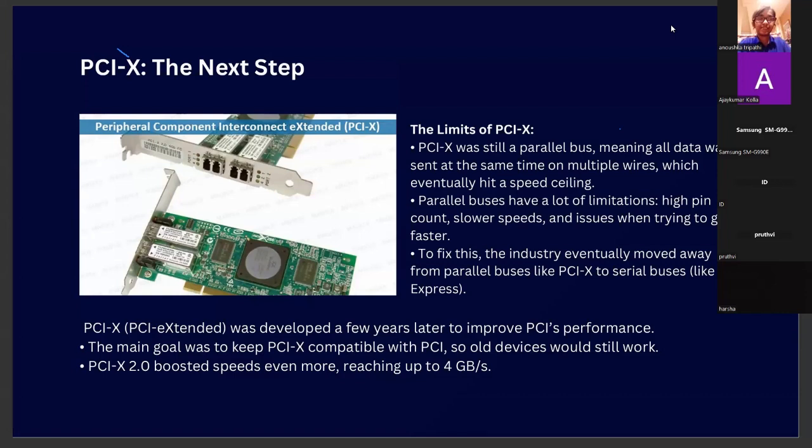But again, as she mentioned, it has a parallel bus interface. That means for every data, the number of data lanes will be more. Additionally, you have to send the clock also from the host to the endpoint. So in the longer run, when the chip is getting shorter and smaller, this is causing an issue. You need a bunch of serial lanes which you have to connect between both devices. Apart from this, you know about the skew, right?